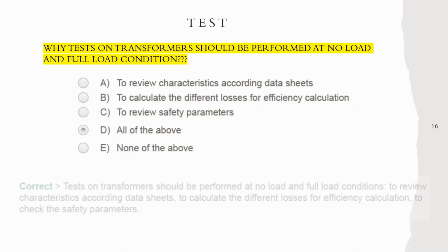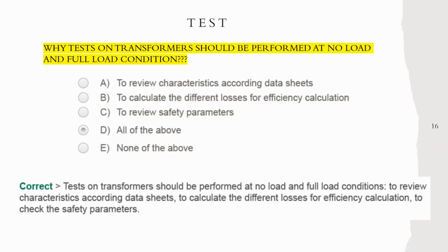Of course, you can see there, D, all of the above. Tests on the transformer should be performed at no load and full load conditions. Always remember that: to review characteristics according to data sheets, to calculate the different losses for efficiency calculations, and to check the safety parameters.